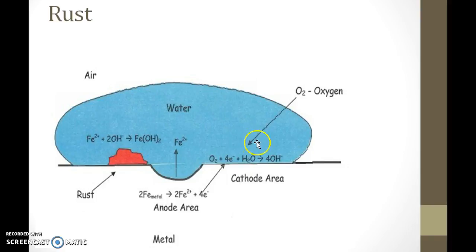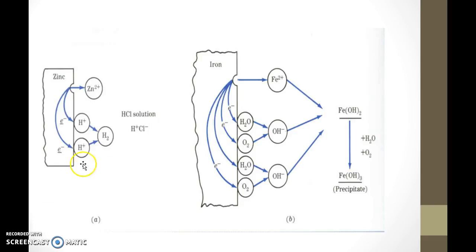These react together to form the hydroxyl ion. Once it becomes Fe2+, the OH- ions attract together and form a primary corrosion product. These primary corrosion products will not stop at the end. So what happens? It will again take oxygen from the environment and go to the secondary corrosion product. See, this is the simple example of the electrolytic dissociation of solution which happens in the system, where